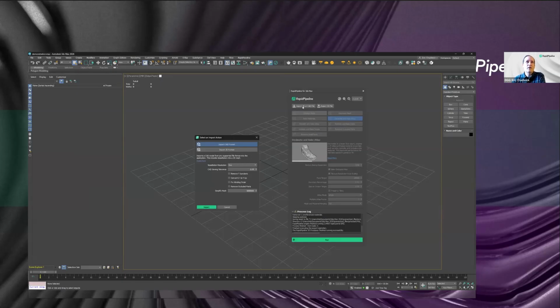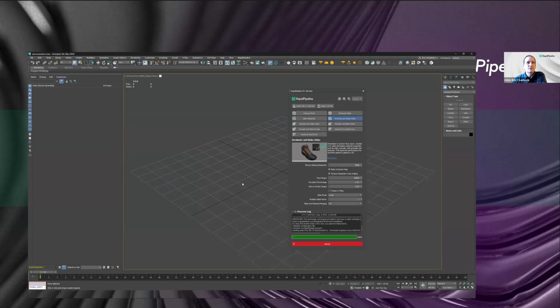When you import a 3D file, you get a bunch of options. You get CAD options for CAD files, and you get 3D format options for other 3D files like this GLB file. There are a bunch of great options here. If you know that the asset is coming, for example, as an FBX file from Maya, and it's Y up there, then you can convert it into the Z up that's used in Max. There are also some USD options so that you can pull in display colors and other things. You can discard a bunch of things if you don't want those. It's all really helpful to give you options about how to pull things in. So I'm just going to choose the defaults here and import it directly.